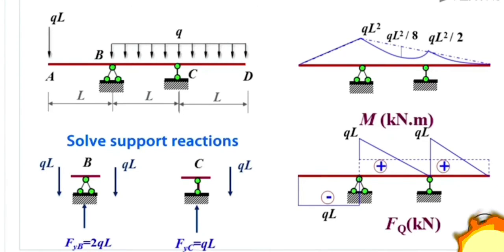Today, we discussed how to construct a shear force diagram according to the bending moment diagram, and then, according to the shear force diagram, how to solve support reactions. At last, you should use the equilibrium condition to verify whether the support reactions are correct.